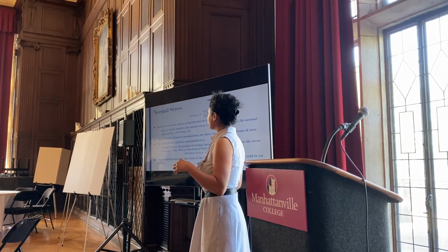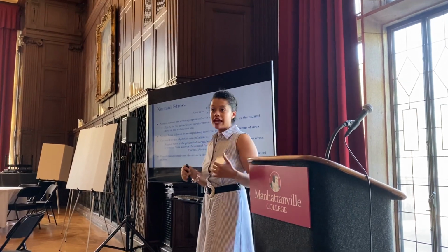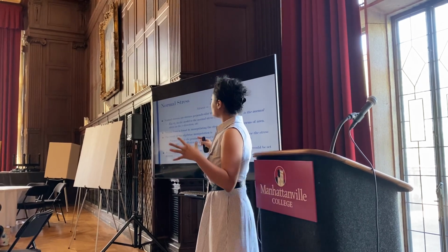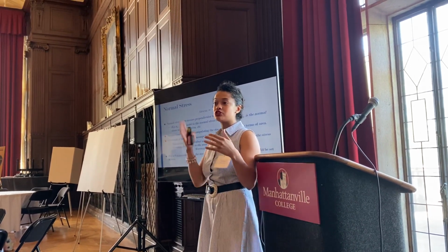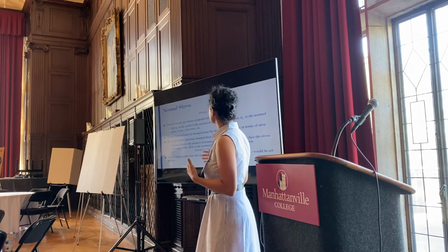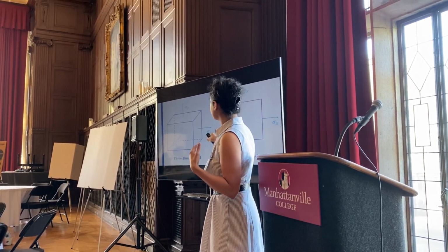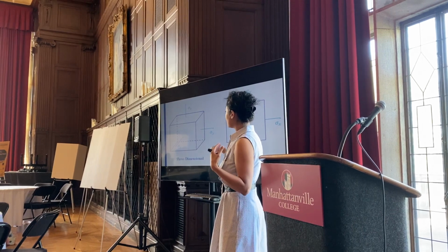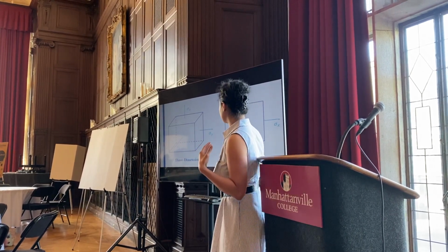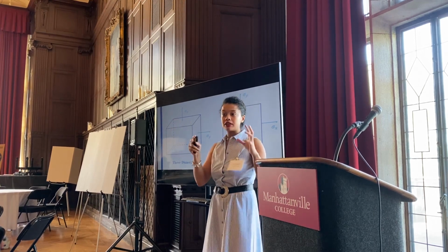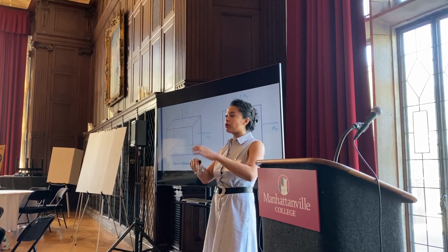Right now in this project, we are dealing with structural mechanics. An important part of structural mechanics is stresses. A normal stress is a stress that is perpendicular to a certain plane. You calculate this by doing the force over the area. Here is an example of a normal stress on a three-dimensional body and a two-dimensional body. Now remember, we're dealing with infinitesimally small elements. So these are tiny things that are part of a larger whole.